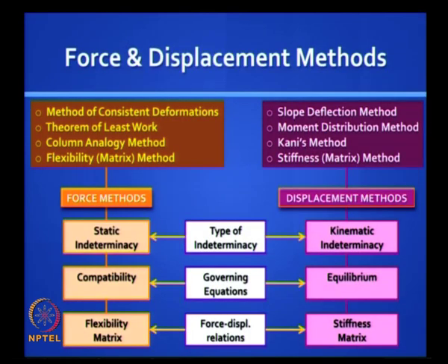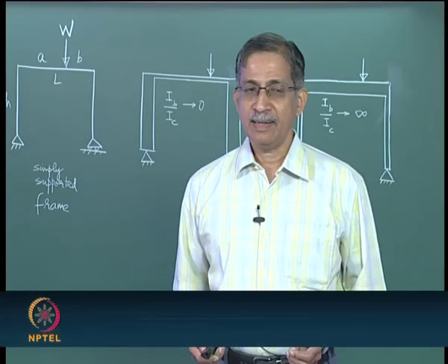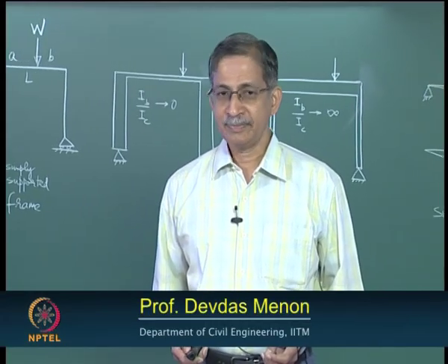In the last class I broadly discussed the basic conceptual difference between force and displacement methods. In this module we will be focusing on two force methods, namely the method of consistent deformations and theorem of least work. If you recall, we had already demonstrated the application of these two methods to solving statically indeterminate beams, continuous beams and fixed beams, to frames, and we also applied it to trusses, right.